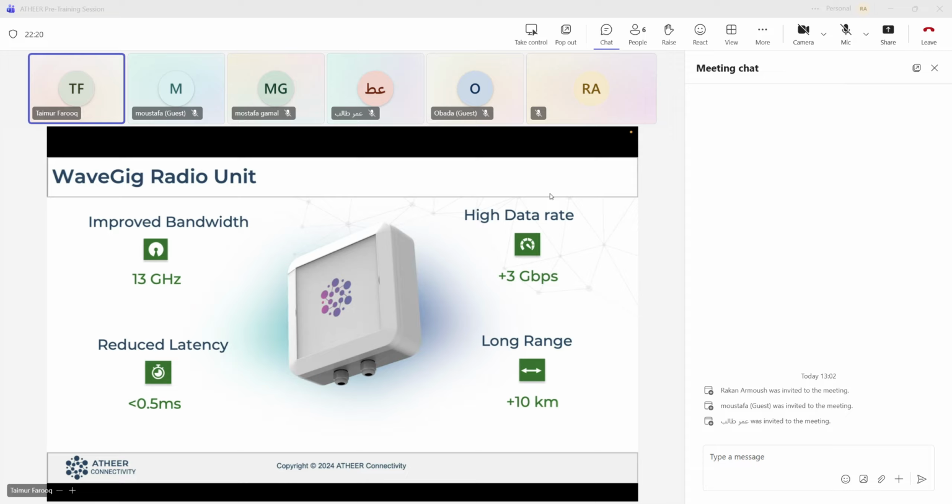So it's a very natural way of growing your network. As you install one subscriber, then a second subscriber, from there you can actually start repeating the signals to the next ones. And the best use case for that is where you don't have line of sight, or the distances are very long, beyond 10 kilometers. You can use this feature.